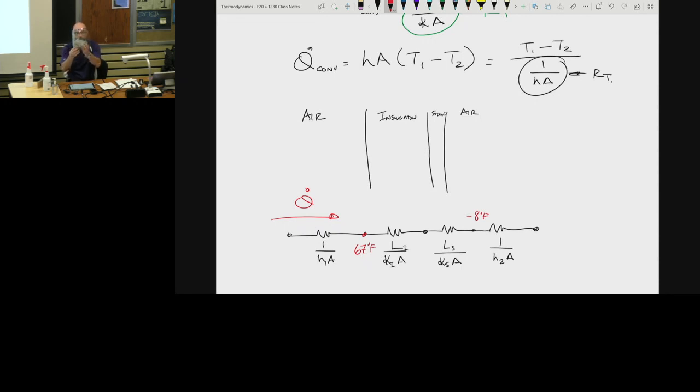The cooler it can be, the better it runs. We don't want to run things over. If we put air through this, we would have one type of h. If we were to put water cooling on the top of this, we'd have a different type of h. If we have laminar flow or turbulent flow, we have different heat transfer coefficients. Our goal would be to cool down our processor to the acceptable range. Okay, this one's made of aluminum. Here's one made of brass. You can see the back of it has some thermal paste on it. We deal with this stuff all the time.